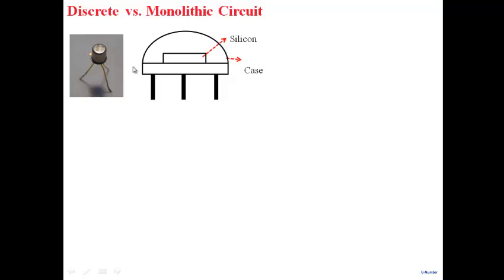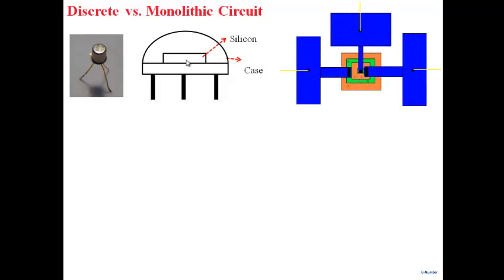If you could go inside and see, what you would find is a small piece of silicon inside this particular chamber. If you examine this transistor, let's say it's a bipolar transistor, it has an emitter here in the center, and then the base, and then the collector, and all of that. The transistor itself is very, very small. Even the early transistors were, say, 100 micron by 100 micron. So a very, very small transistor here. And one can make it even smaller. One can shrink the geometry and make it smaller.